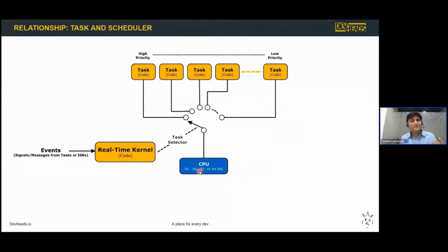And that depends on the priority. The third part is priority. Because there will be some tasks that have a higher priority and some tasks that have a lower priority. So the scheduler makes a decision of which task to execute. So that's how multitasking is possible using FreeRTOS on the Cortex-M microcontroller, at least for what we wanted to do.